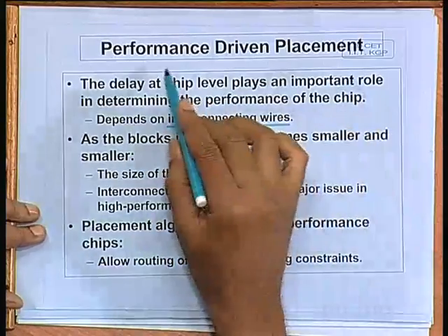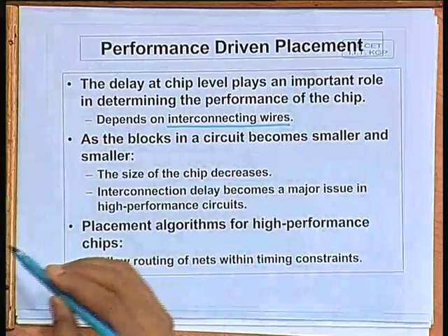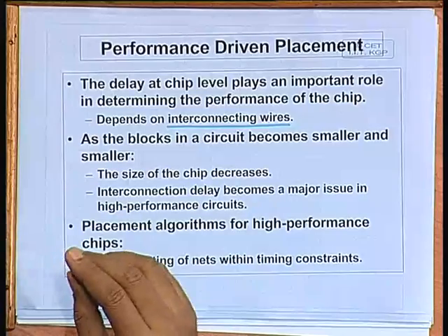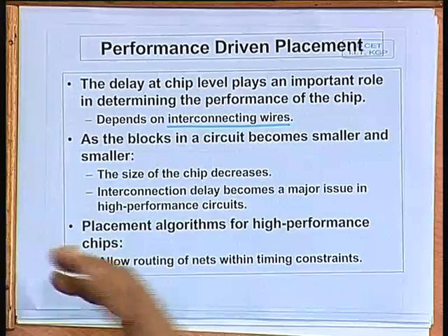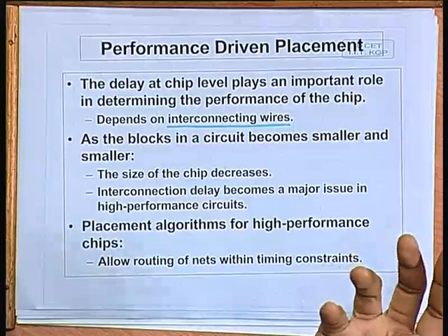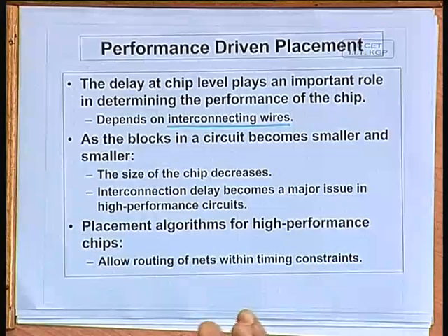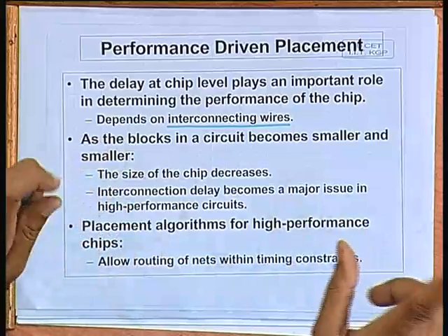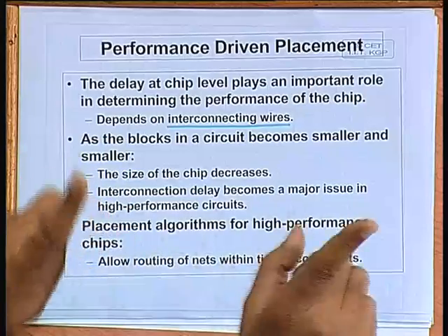See, this performance driven placement has become important in the modern day scenario because today in a VLSI chip, the size of the basic components, the gates or modules, whatever you call, they are reducing in size, their speed is also increasing. Now, in comparison, the interconnecting lines have also become very narrow and they are very closely spaced together, there are some other parasitic delays which are coming into the picture.